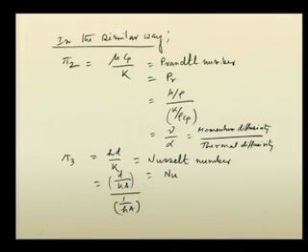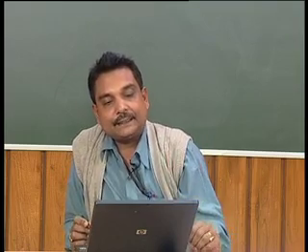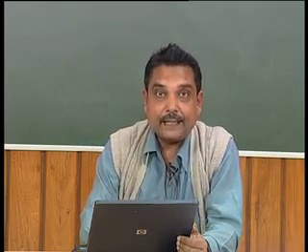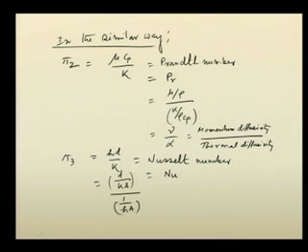So, I have just incorporated one area term over here. So, then it can be written like this. We are multiplying up and down by an area, so we will get it like this. This we have already seen: L by K A is called conductive resistance. K is the thermal conductivity, and D by K A or L by K A, where D is the characteristic length, here it is the diameter. So, D by K A is the conductive resistance, and 1 by H A is the convective resistance. So, it is becoming a ratio of two resistances.